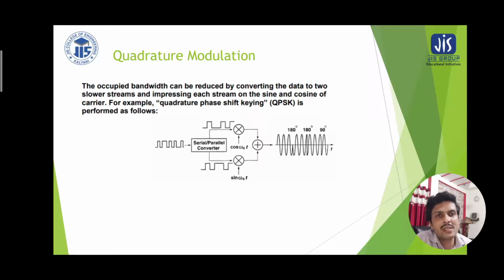Now in this case, sometimes the clock frequency also has some additional circuitry, so that the even bit and odd bit can be separated. Therefore the serial to parallel converter is a block of circuit in which the clock is specially treated so that it is able to differentiate the even bit and odd bit. There is a toggle flip-flop having complementary clocks. That means in one path we get rectangular clock pulses, and in another path we get the complements of those clock pulses. So when one bit is 0, the other bit is 1, and when one bit is 1, the other bit is 0.